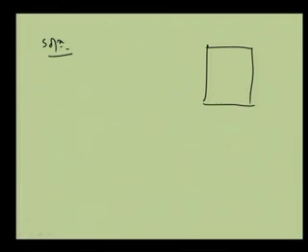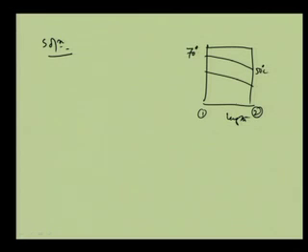Now, to start with the solution, just a rough sketch of the temperature profiles. If we see this length, this is station 1 and this is station 2 of the double pipe heat exchanger, and it is counter current flow. So, here it is 50 degree centigrade, and then it is 70 degree centigrade, and then here it is 30 degree centigrade, and there it is 40 degree centigrade. So, this is delta T 1, it is 30 degree centigrade, and here it is 20 degree centigrade.